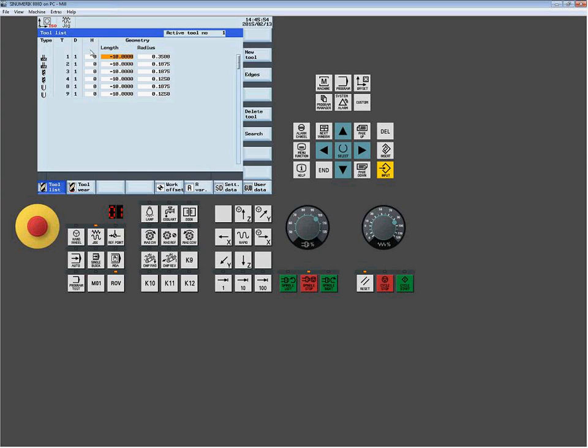The H column is required to be able to start running the part programs. The way the H column works, and you'll see it in the part programs as you open them, is it's generally matched to whatever the tool number is. So if it's T1, it's going to be H1, T2 is going to be H2, and so on and so forth. It doesn't have to be, but that's typical standard. So I set up my H's now while I'm in this screen, which keeps me from having to do it later.